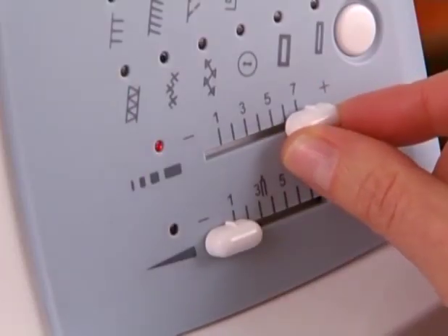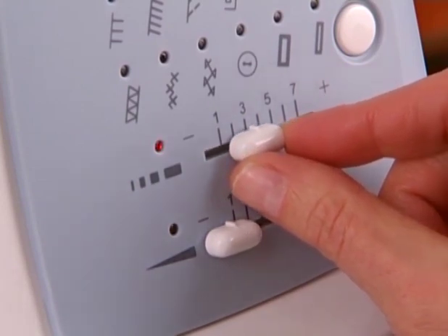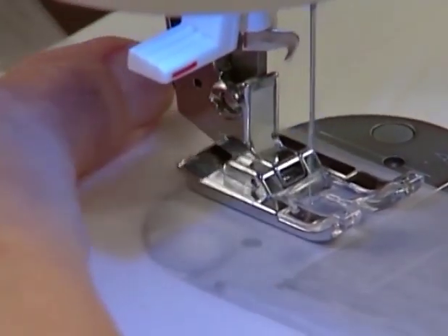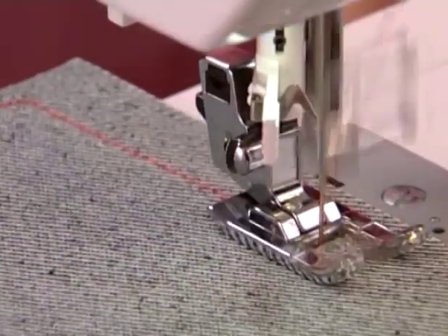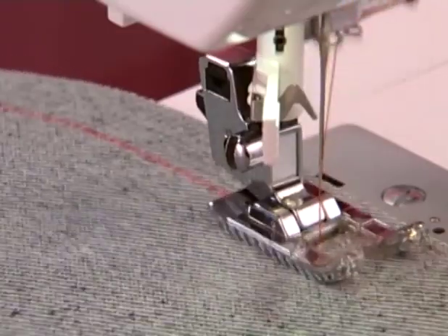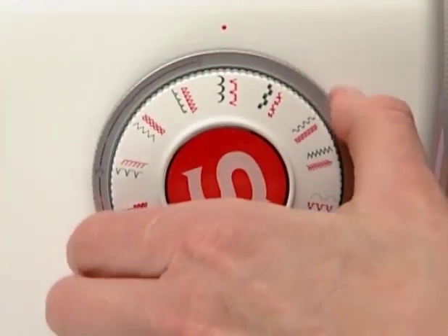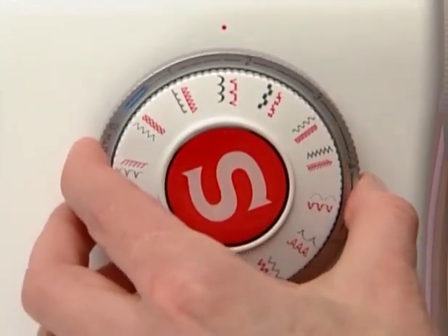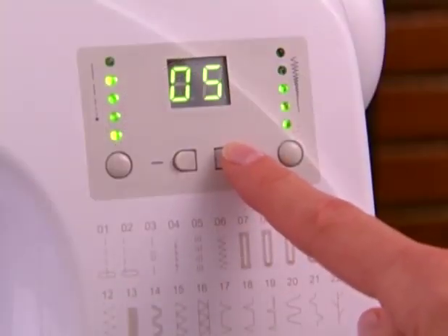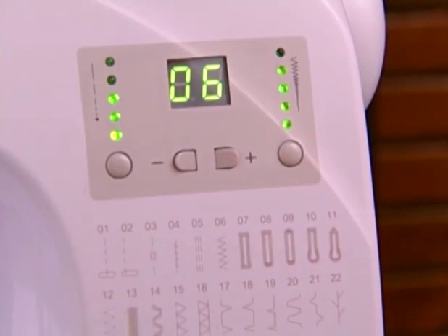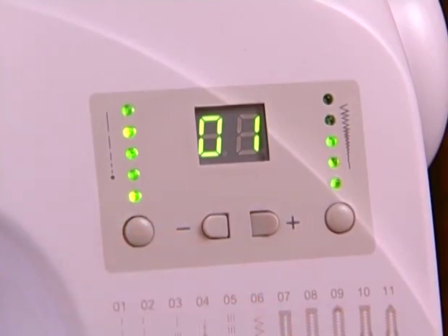The stitch length control can be adjusted to sew stitches shorter or longer. Shorter stitches are better for lighter weight fabrics or when you are working with a finer thread and needle. Longer stitches are better for heavier fabrics or thread or when working with a larger needle. On mechanical machines, stitch length is adjusted by moving a dial. On electronic or computerized machines, though the optimal setting is set upon selection of the stitch, further adjustment of the stitch length is done with either a lever or with push buttons, depending on machine model.